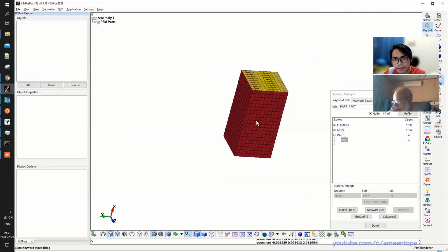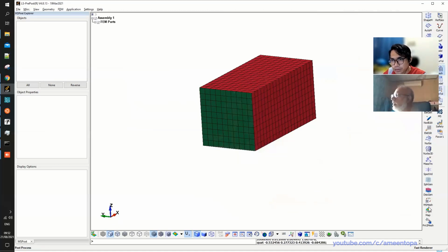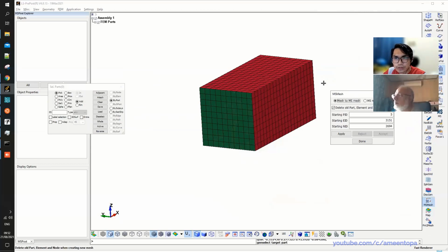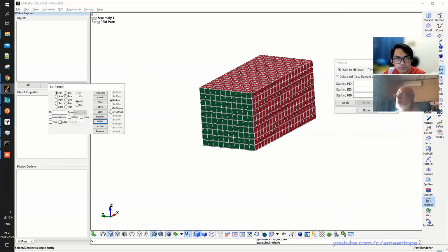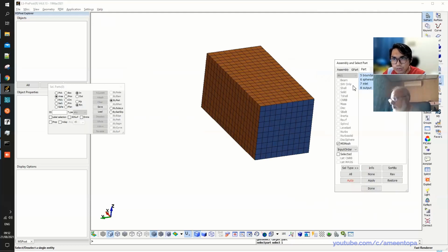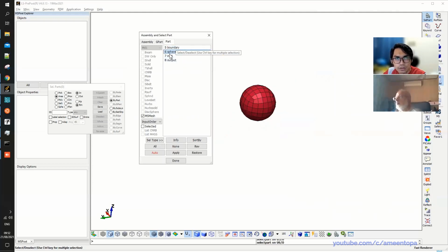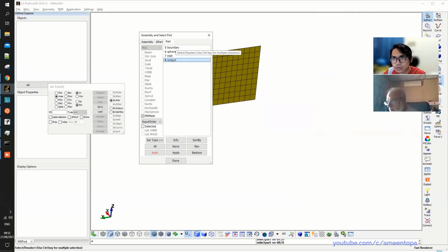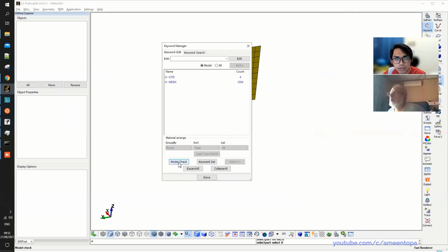So now I go to mesh, multi-solver. So convert the mesh to multi-solver. Click on whole. We have 4 parts, 4 shells. So that's correct. Apply and then accept. So now click on F2. You'll see we have MS multi-solver mesh. So this 5 is the boundary, 6 is the sphere, 7 is inlet, this is outlet. Okay, good. So now let's go to the keyword very quickly.